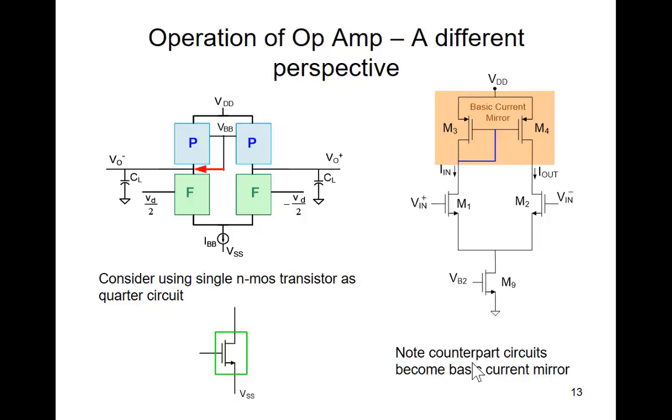You assumed non-zero current going into those gates of those counterparts now, right? Yes. If you don't have non-zero current, then you don't have a perfect current mirror. If you have a bipolar device, you have a little base current flowing, for example. But if there's no current that flows here, then this current and this current, if we set it for a mirror gain of 1, will be the same. They'll be the same DC-wise, they'll be the same small signal-wise. Did I answer your question?